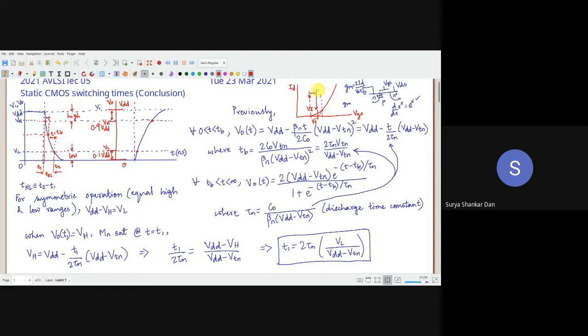This is obviously, you can call it as the overestimation of the threshold voltage, correct? Threshold voltage actual is here, मतलब यहाँ से यहाँ तक. Now you are overestimating it from here to there. From leakage point of view, of course, that is less. Power consumption would be high, sir. Obviously, that is also power high. See, the leakage power तो कम हुआ, definitely, as your friend has rightly said.